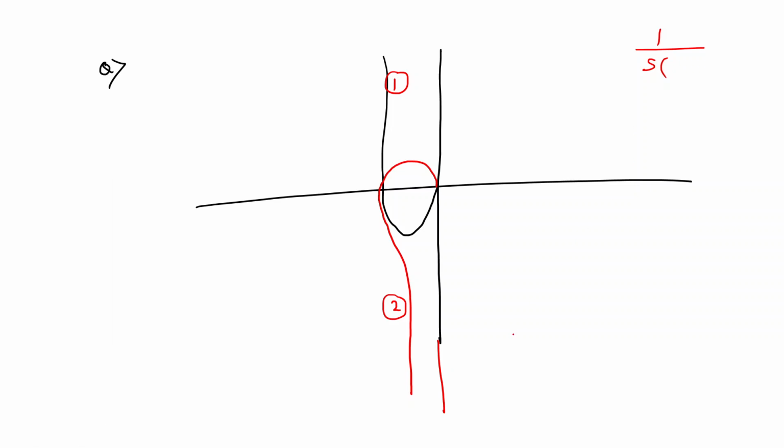But you have to start at this point, right? Because this is the polar plot one, and this is the mirror image 2. So you are now reaching at this point, so you have to start that infinite radius half circle from this point. I told you, you have two options: clockwise and anti-clockwise. But the Nyquist criterion says the infinite radius half circle is always in the clockwise direction. So you have to make a clockwise circle like this, right?